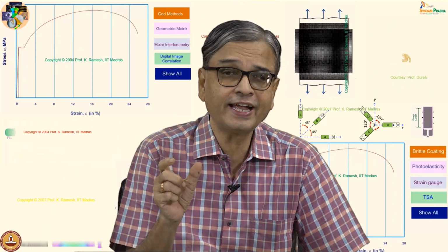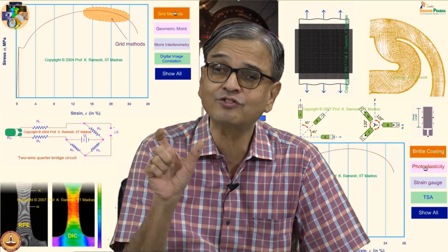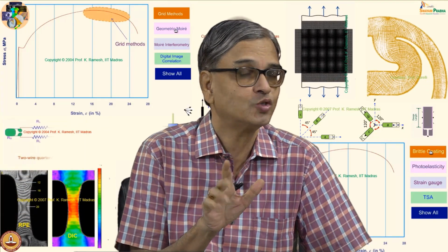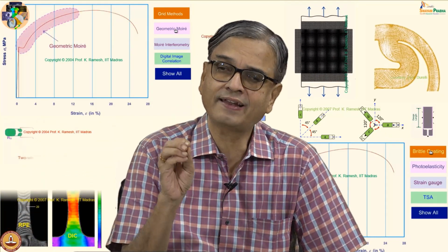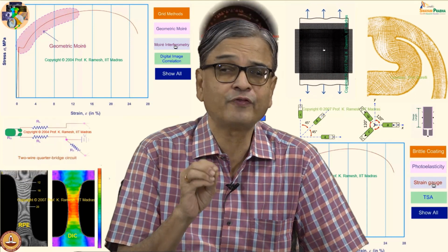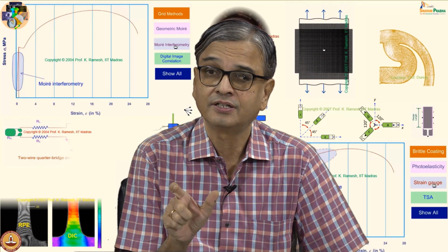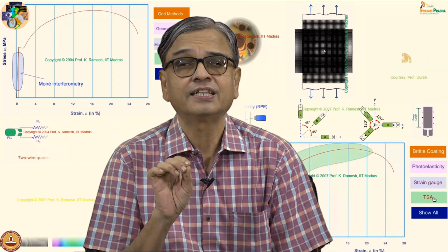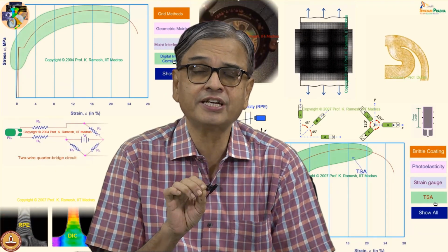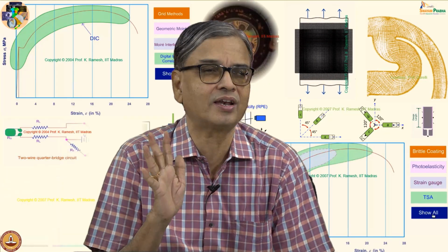But you also find the range with which these measurement methodologies can be used, they also keep reducing. So, in any measurement system, you have a resolution. If it is of very high resolution, the range is also limited. Is the idea clear? And you have to be sensitized that we are attempting to measure the quantity strain which is extremely small.